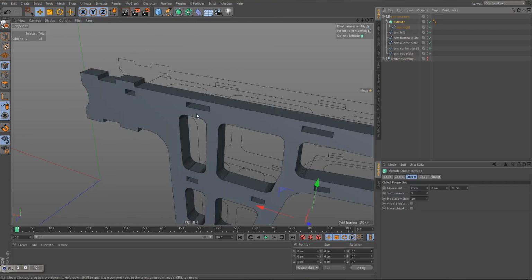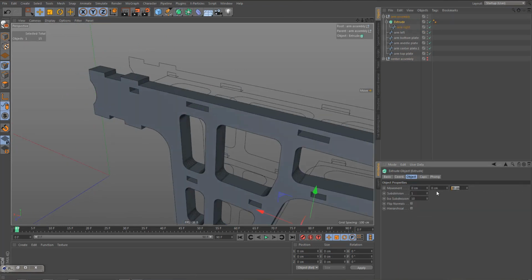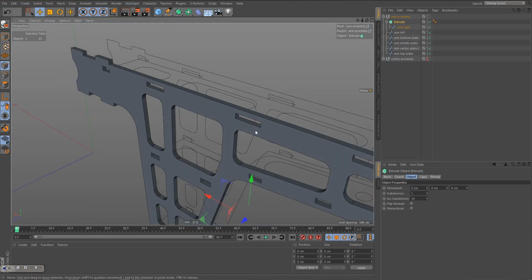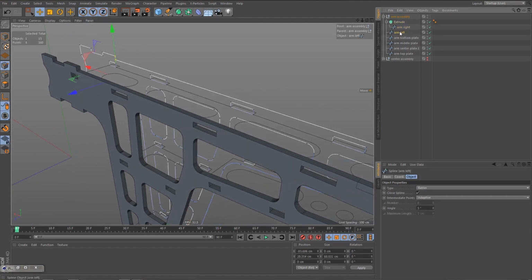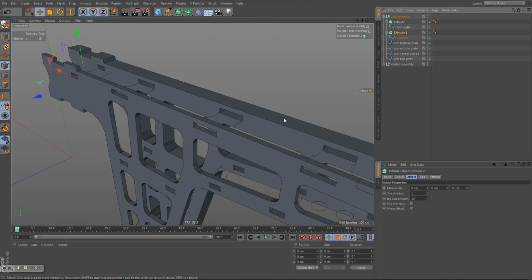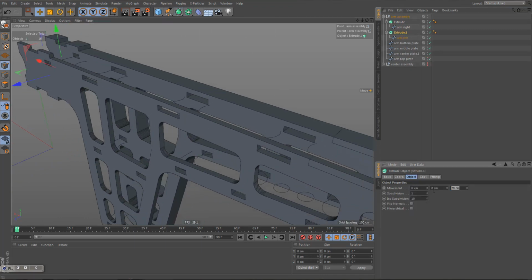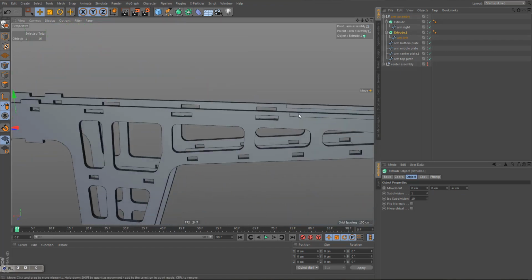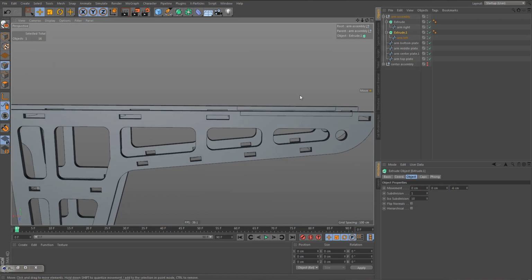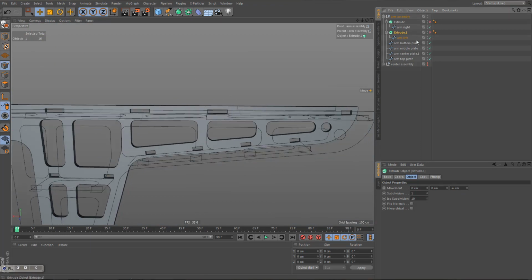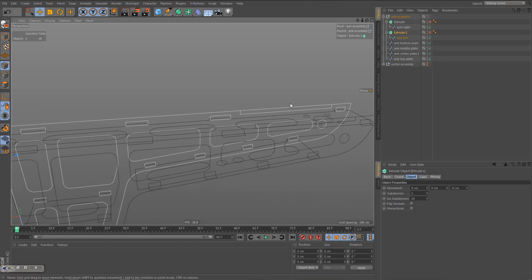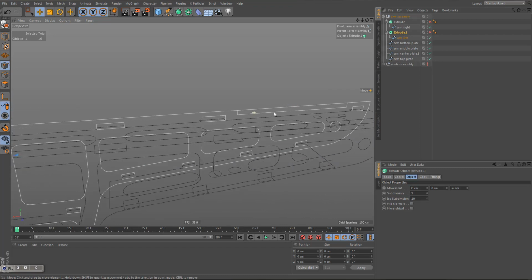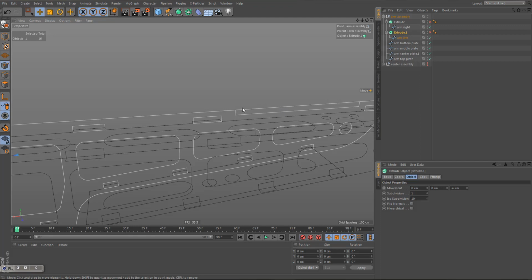Let's put it in an extrude object, and we need to extrude this 6 centimeters, and this arm we need to extrude -6 centimeters. And we have another issue here, that is I do, hopefully you don't. When I fixed these splines, apparently I made a couple of mistakes. So over here we need a cutout, and something's wrong because we have a line here, and also down here we need to get rid of this one.